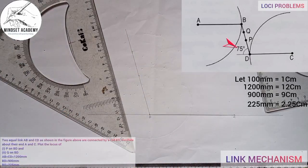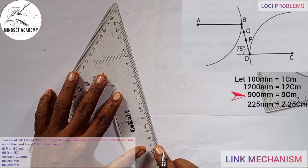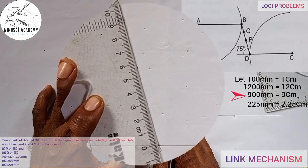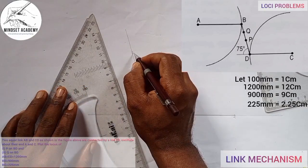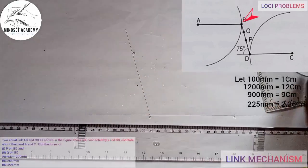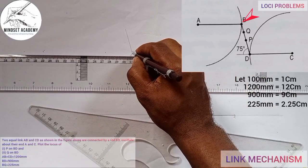Now we're given that BD, right, is 9 centimeter. Instead of the normal 900 millimeter, we've converted it, so we're making use of 9 centimeter. So I'm going to measure 9 centimeter from this point. From 0 to 9 is 9 centimeter. So from 0 to this point 9 here, this is our 9 centimeter here. So that will be point B, right? So from that point B, I'm going to draw an inclined line this way.